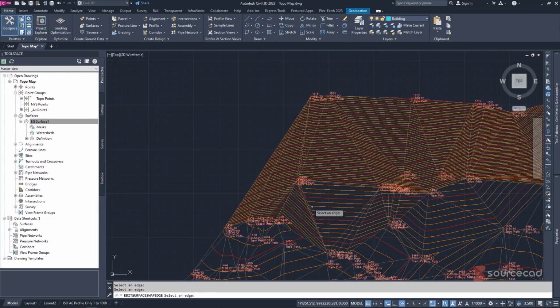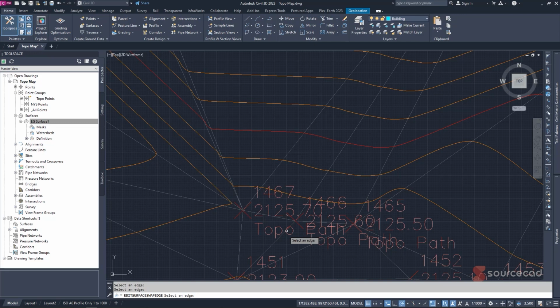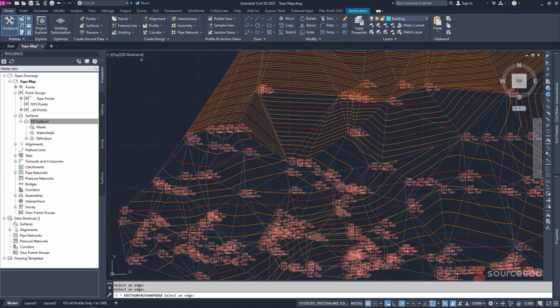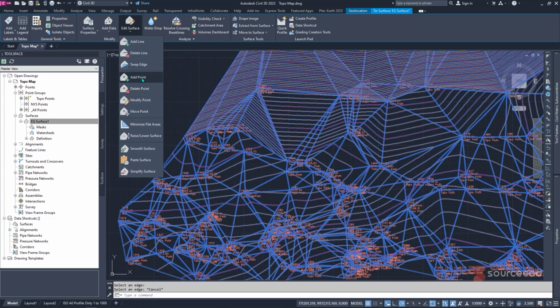So it depends if the edge can be swapped or not. So in this case, that specific area cannot be swapped, and that's the way you usually check. So sometimes it can be applicable, sometimes it cannot be applicable. So once that's done, you can also check other options. You can either add points. Maybe here there's a missing point.